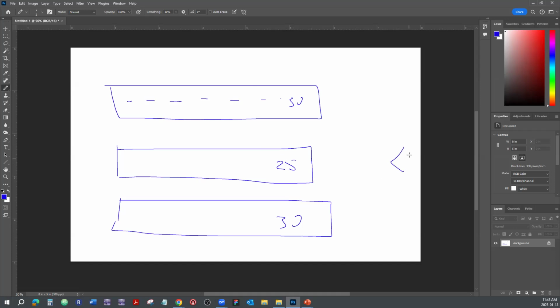The amplifier wants to see 8 ohms. Each speaker is 8 ohm. Can you connect all those speakers in? You have to draw it out, and you have to do series parallel. You can do a little bit of spider work, and you can accomplish 8 ohms out of all those by doing that trick with series parallel combination.